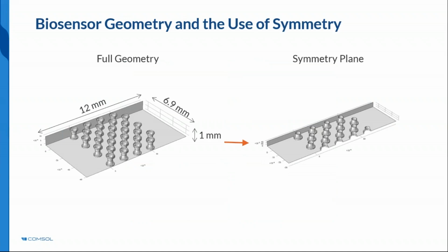The pool geometry has symmetry planes which can be used to reduce the simulated system size. Reducing the size of the system and using symmetry boundary conditions will lower the number of mesh elements required, and thus lower the computational requirements. This can yield faster simulations without any loss of fidelity. The full geometry can be restored from the reduced geometry in post-processing using mirror data sets.